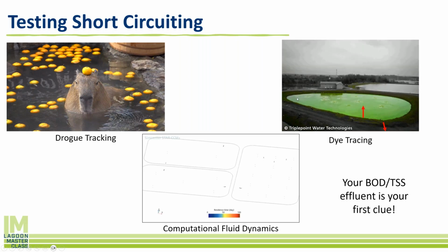We thought the influent of this lagoon system was right here, but there were no as-builts. And when we finally did the test, you'll see that the influent is all of 25 feet away from the effluent. So we learned very quickly that the dye shoots up here and shoots right for the effluent, and we diagnosed an issue pretty quickly with dye tracing.